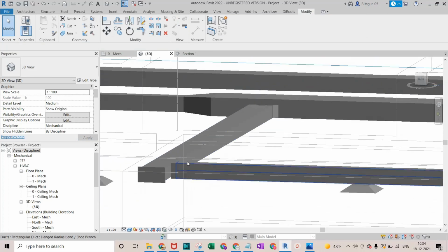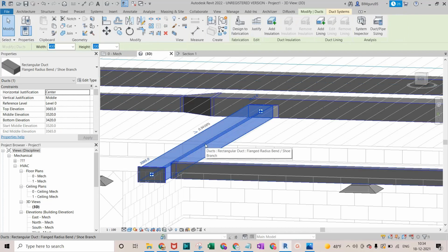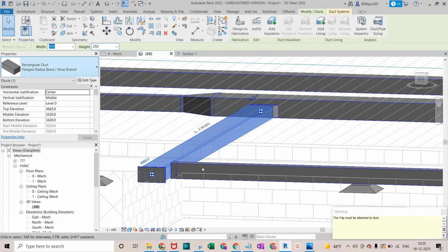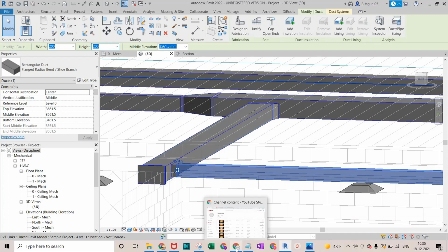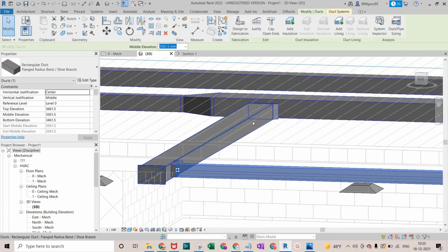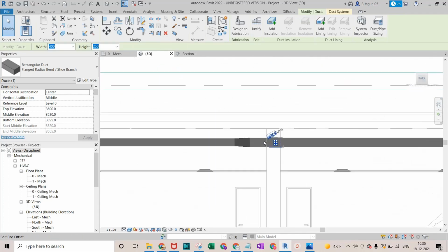Okay, the duct size has increased or what? And this duct size is okay, that's 400 by 200, and that was the concern. I told you earlier that it should be minimum 250 and 200. Please take care of that thing always, and we can now raise this up.